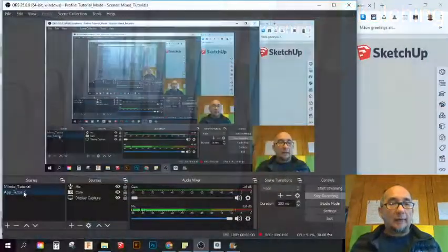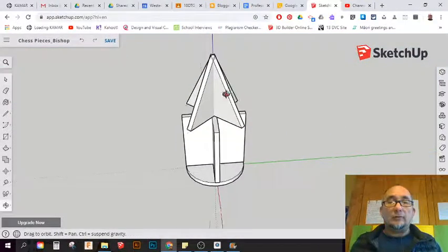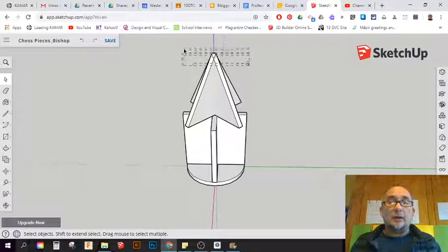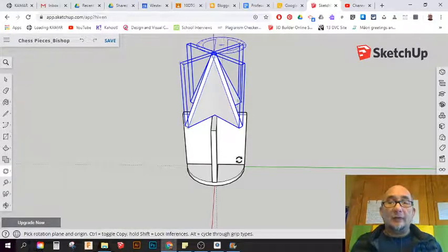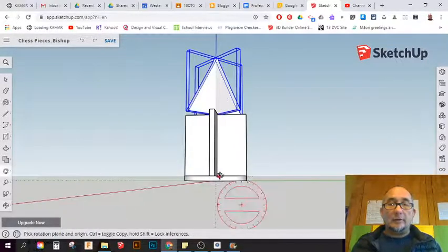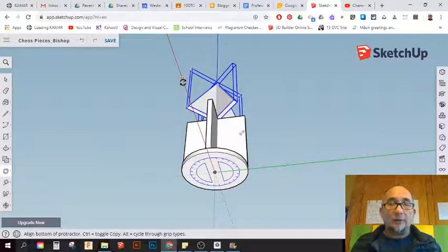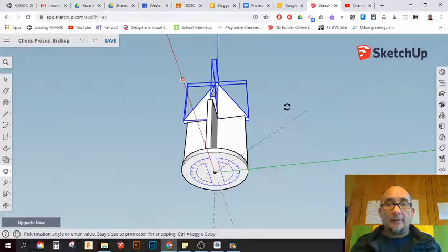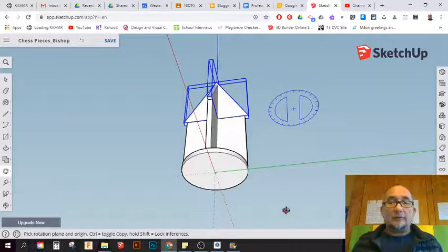So I'm going to go back to here, and so the first thing to do is to change this back, right? So to not be at 45 degrees. So I'm going to use my rotate tool. After having selected these pieces, I'm going to go to the origin because that makes things a little bit easier. So look at it from underneath. Please excuse the lag. This is part of what happens when you use the online version. I really recommend, if you are going to be doing a whole lot of SketchUp stuff, that you download that. Right, so 45 degrees. Enter it, so that's better.